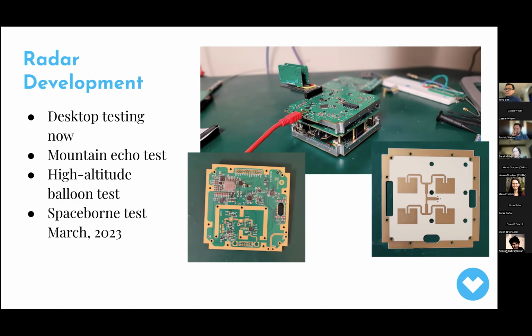But I'm not sure. Once you start going to L-band, you typically see these larger deployable systems that start to be very expensive. Right. And the advantage of having smaller satellites is also to capture extreme events, right? With more frequent sampling, but the C-band has its limitation. Right. Though there is some work in dual frequency, in cross polarization, right? Yeah. And cross frequency, which I think even in C-band could have some potential for higher winds, and also would be more feasible from a small satellite. It would be easier for us to add another antenna on that surface than it would be to add a 5 times larger antenna.